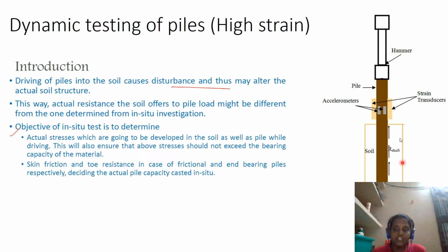So once you finish driving your pile and you apply the load, because of the changes that have occurred to the surrounding soil, or because of the changes that have occurred in the pile itself because of stresses created during the driving, the pile is not going to give the same strength that we calculated. We have to check whether the stresses that are developed are within the allowable limits.